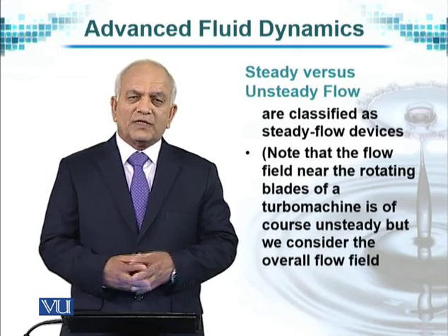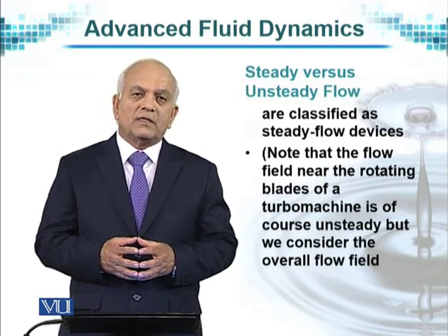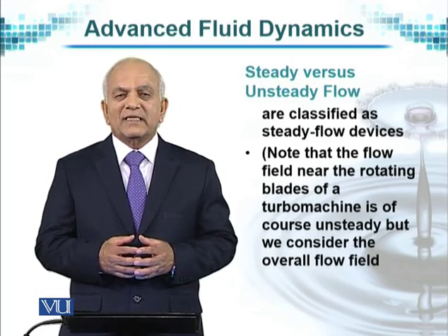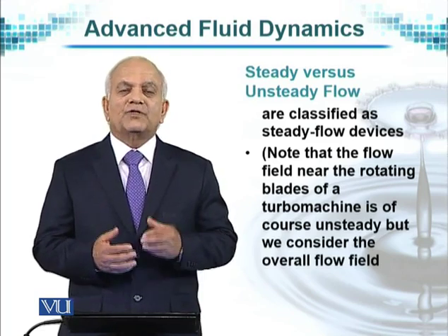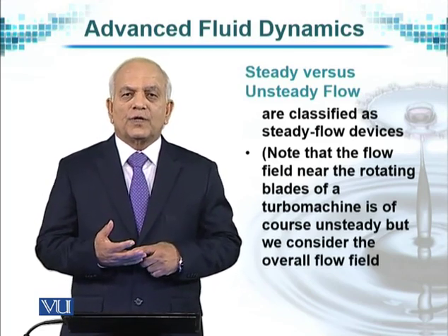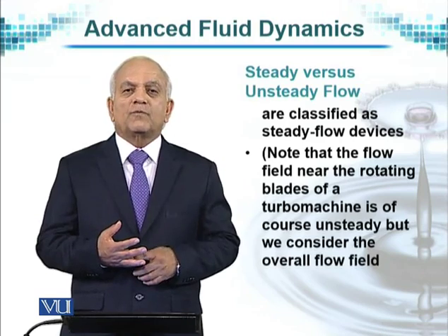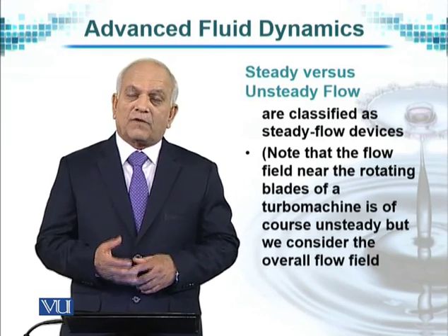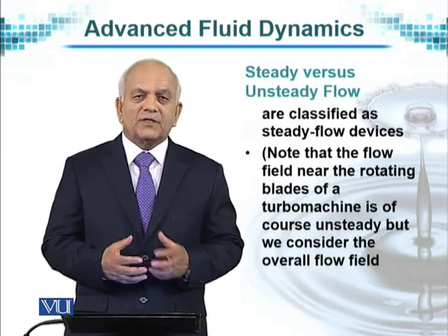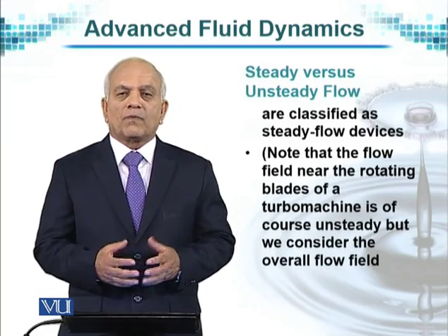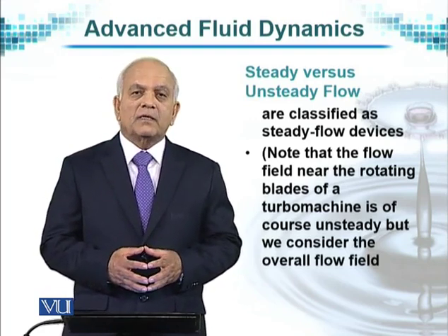It's important to differentiate between all these terms, because when we model our equations and analyze fluid flow conditions, these things are important. We apply them. They have a very significant effect on how we choose boundary conditions and initial conditions for the solution of equations, which is going to predict the flow conditions after, let's say, some time t. So if we understand these differences in the physical phenomena properly, then its mathematical modeling and its solution also become that much clearer, more accurate, and better.